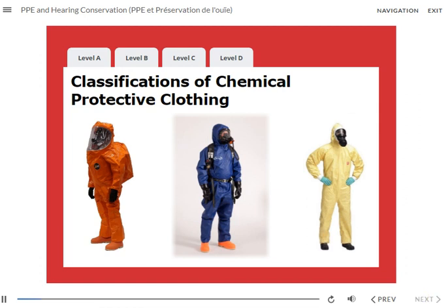Since hazards vary, the selection criteria will be based upon the physical, chemical, and environmental hazards that are present. Remember, chemical permeation is always used to decide the right chemical protective equipment. If there are any questions about the selection, inspection, or use of PPE, always ask your supervisor or health and safety representative for clarification. Chemical protective clothing is classified by 4 different levels. Click the tabs at the top of the screen for an overview of each level.